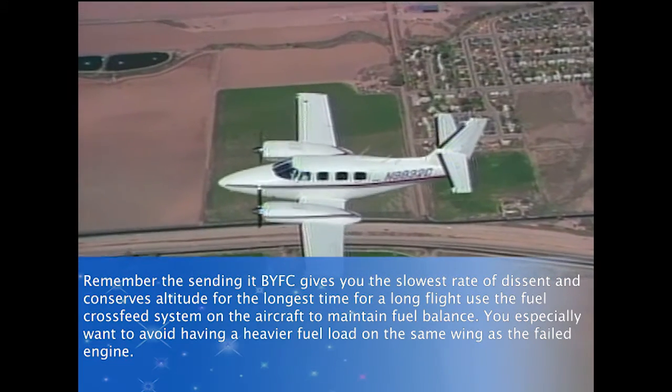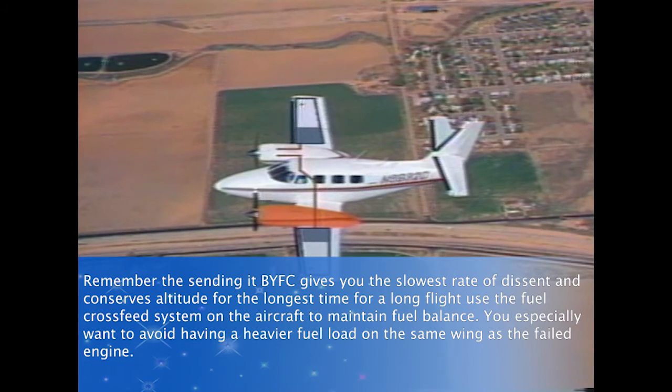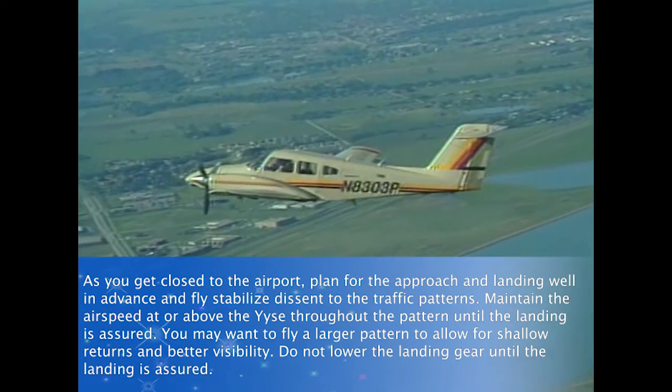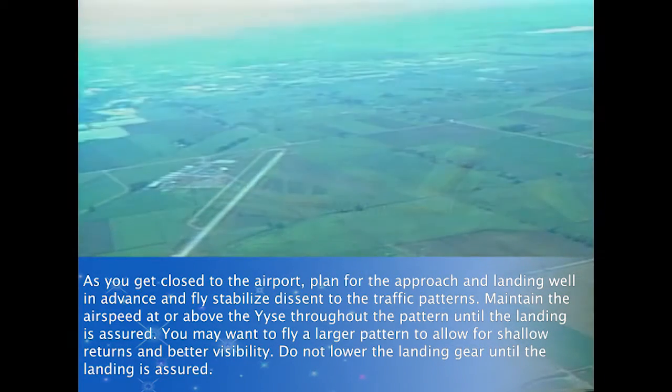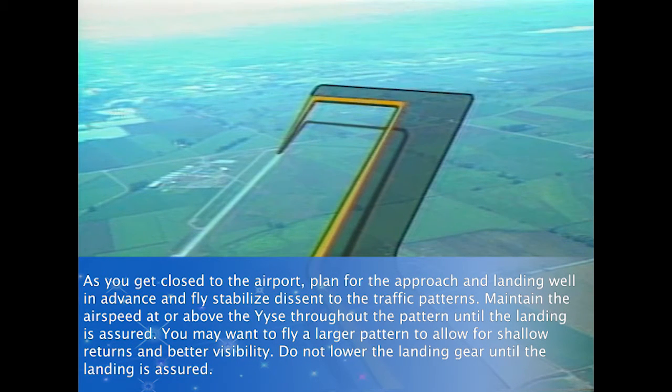For a long flight, use the fuel cross-feed system on the aircraft to maintain fuel balance. You especially want to avoid having a heavier fuel load on the same wing as the failed engine. As you get close to the airport, plan for the approach and landing well in advance and fly a stabilized descent to the traffic pattern. Maintain the airspeed at or above VYSE throughout the pattern until the landing is assured. You may want to fly a larger pattern to allow for shallower turns and better visibility.